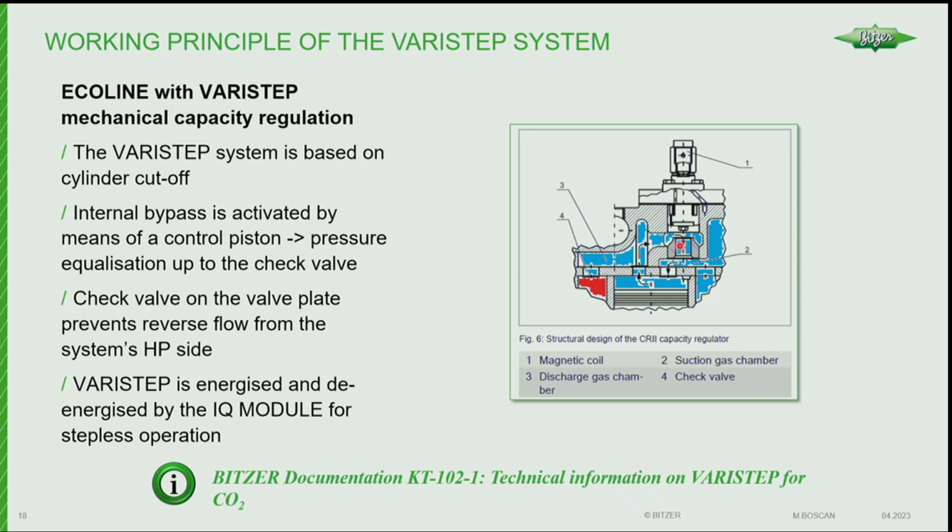But it's simple, it's really easy to understand, really easy to parameterize compared to a VFD, and it's very difficult to bypass. I mean, I say difficult. It's less of a reason to bypass. You can just pull the coil off and you've bypassed it, but it's easier to troubleshoot and diagnose. And it's easier to know exactly what's going on, too.